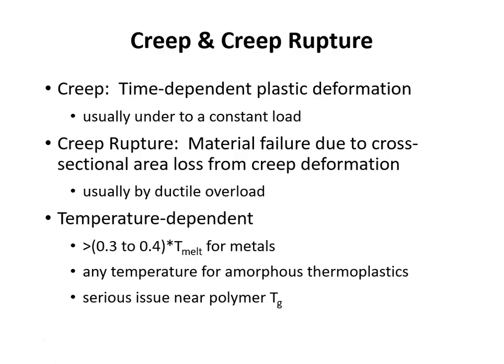So the general broad descriptor of creep is a time-dependent plastic deformation. Again, this is very similar to viscoelastic flow, and it is defined as time-dependent, plastic, not elastic, deformation under a constant load. Stress relaxation would be its counterpart. If we had a material and we imposed a known displacement and then looked at its load relaxation due to these types of high temperature mechanisms we'll be discussing, that would be the same kind of scenario.